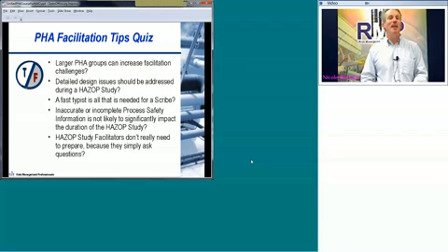So you can waste a lot of time with inaccurate P&IDs. It's always a good idea before the HAZOP study to go back through and properly field verify and update the P&IDs so the team can focus and work efficiently.